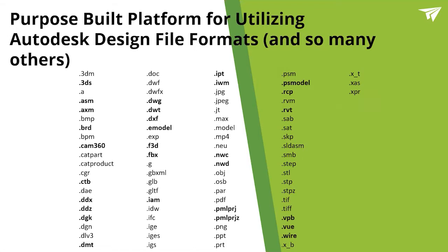In the case of BIM Collaborate Pro, being able to host your Revit Central model in your cloud project, with multiple different contributors opening and editing that model simultaneously through the use of worksets. And then also being able to leverage just the web interface or even the mobile device to go in and view these different files that are being stored up there, even if it's somebody that doesn't actually have a license of Revit or have the software installed on their machine. They can go in there and actually view and see the progress that the model is taking over the course of the project, and they can do that from within the web interface or even on the mobile device.